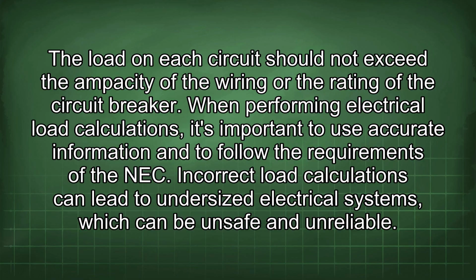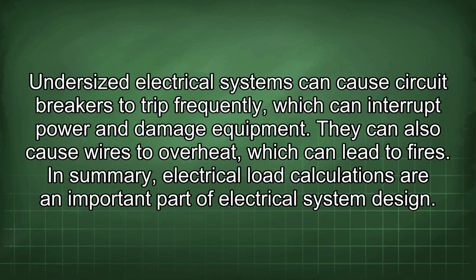Incorrect load calculations can lead to undersized electrical systems, which can be unsafe and unreliable. Undersized electrical systems can cause circuit breakers to trip frequently, which can interrupt power and damage equipment. They can also cause wires to overheat, which can lead to fires.